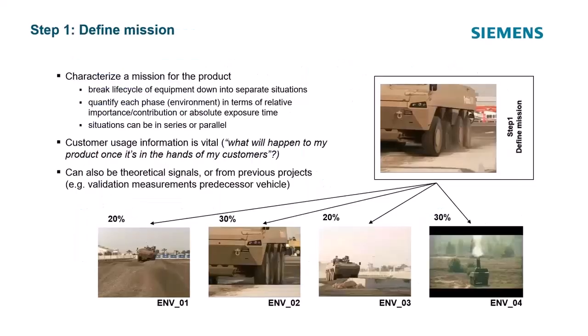To me, this is the hardest part because you have to know the loading environments that your product sees over the life. So you need to break the life of the product down into X number of loading environments in this case and you need to know how much time it spends in each one of those loading environments. Because we're going to get the damage from each one of these scaled to the time, and then we're going to combine them all together. This could be the hardest part. The data we take is fairly simple, but you really have to know your product and how it's used.